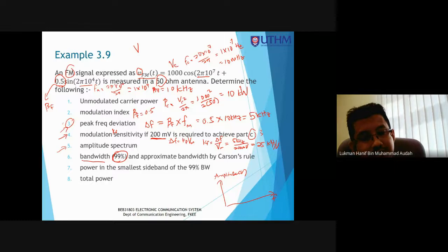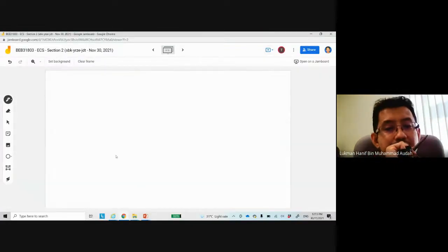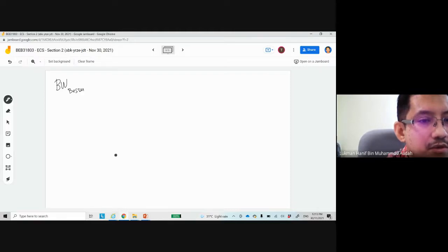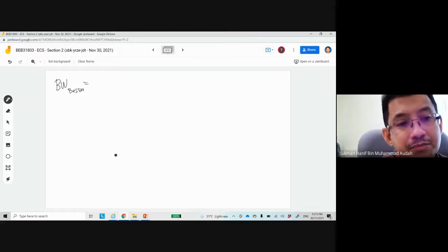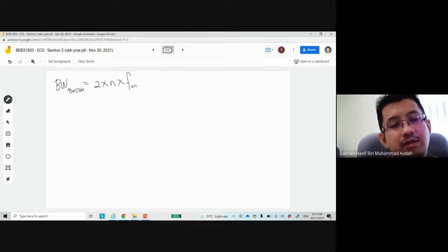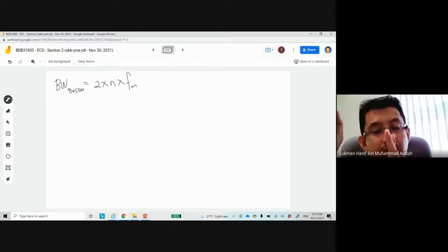So what you need to do is, first of all, find bandwidth by Bessel, which is equal to 2 times n times Fm. We already know how much is n. N is 2.